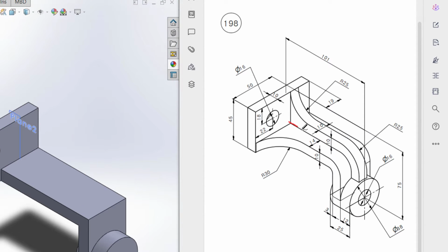In the same way we can see we have another upper rectangular portion. Okay, and for drawing this upper rectangular portion, first of all I will select this line and this other line, then I will convert these two lines of the previous rectangle, then I will offset it into a line of 10 distance. Okay, then I will extrude it to 10 unit.